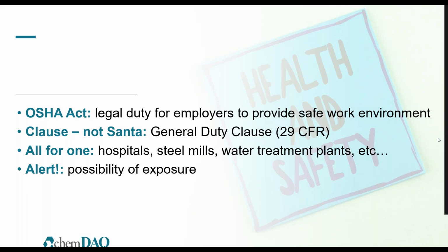So if for an hour you're exposed to 2.0 and then an hour you're exposed to 0, obviously over that time frame you're averaging out to 1.0. But they look at that average over 8 hours. So ethylene oxide and hydrogen peroxide, they have a 1.0 parts per million regulation over 8 hours. So if you take an 8-hour sample, what is your exposure to those chemicals?